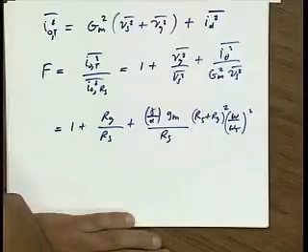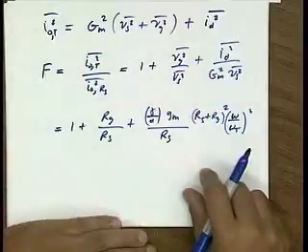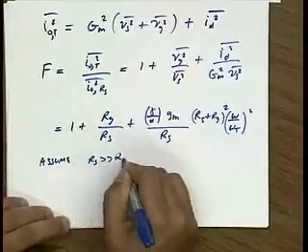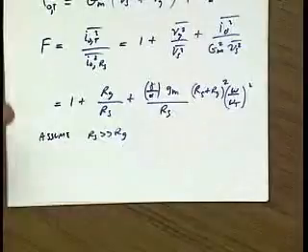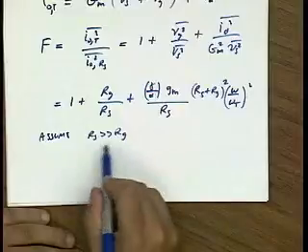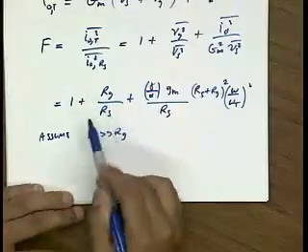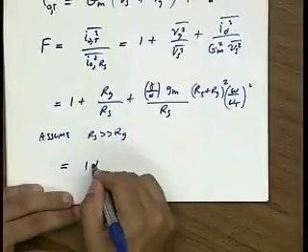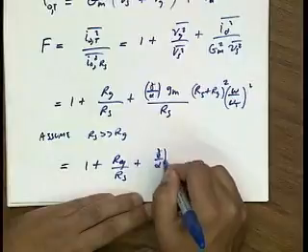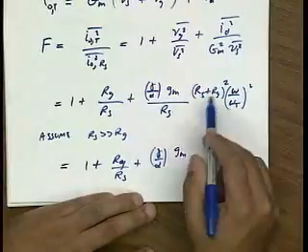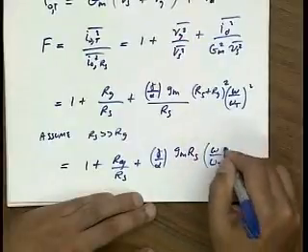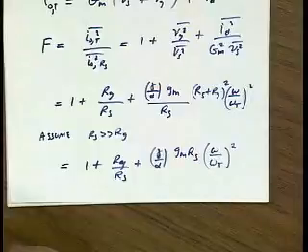Okay, now you can see that there's some simplification in order here. In particular, let's assume that Rs is bigger than Rg. Otherwise, we'd have a terrible noise figure, right? So let's assume that we're at least a factor of 5 or 10 bigger than Rg, because we don't want this term to contribute to the noise figure. And so then we have F is 1 plus Rg over Rs, gamma over alpha. Gm, here I have Rs squared, here I have Rs, so I just get Rs, omega over omega t squared. And this is the same expression that we derived last lecture.